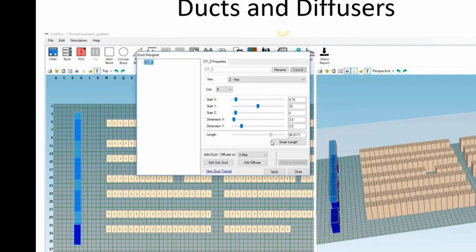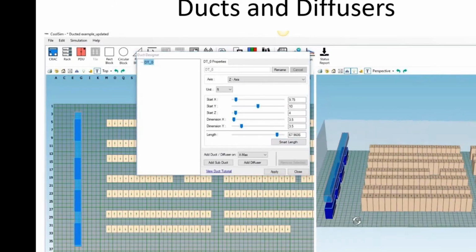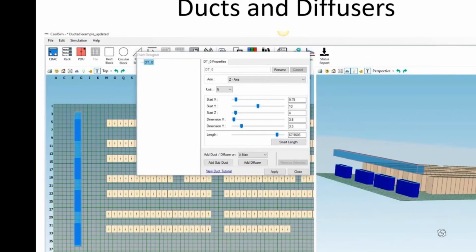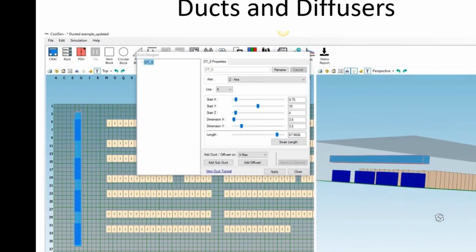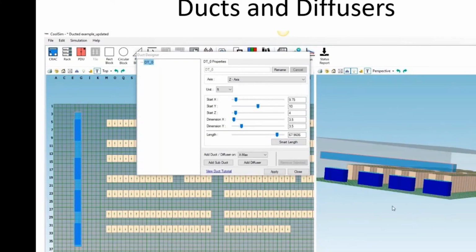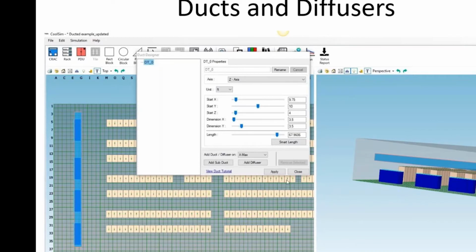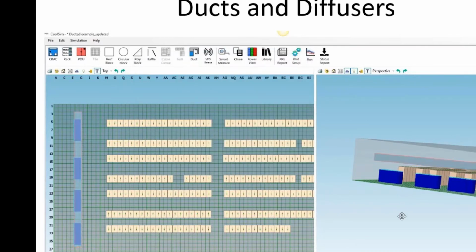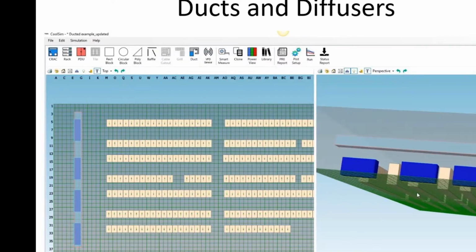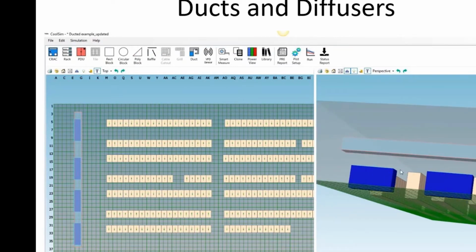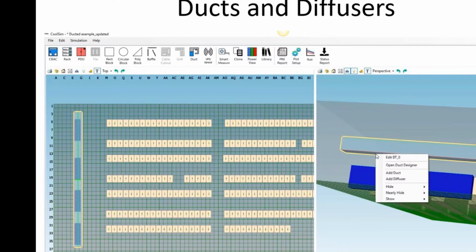And I'm looking at the left-hand image to see what it looks like in top view. I'm looking at the right-hand image to see what it looks like in the side view. I can manipulate either one of these by moving the mouse back and forth from one to the other. They're synchronous, so what I get in one is the same as the other. And it's a nice way, particularly if you've got two monitors, to interact with a 3D model and understand where everything is without having to flip it all over the place.